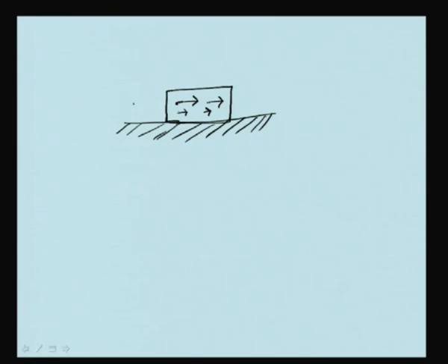If we pick up 2 points on the body and draw lines perpendicular to the velocity of the point and passing through the point, the 2 lines will be parallel. Here one perpendicular line, one another perpendicular line. The 2 lines are parallel and they never intersect. However, we can consider that they intersect at infinity. Thus, the instantaneous center of rotation of a translating body is at infinity.